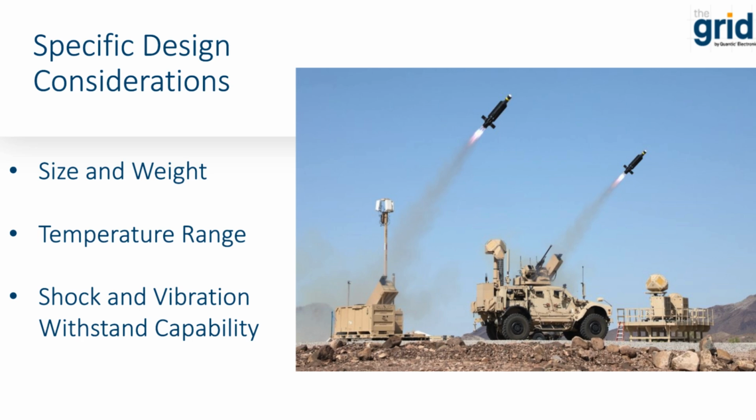Having a true understanding of the energy density and power density of a capacitor option helps to ensure this is met. Now, the environmental conditions a capacitor faces when deployed are a key part of the selection criteria. Different capacitor technologies have different temperature ratings, so attention must be paid to the capacitor's temperature range during selection. Capacitors can have maximum temperature ratings between 70 degrees C up to 300 degrees C, which must be considered. Some capacitors even require voltage derating above a specific temperature limit.